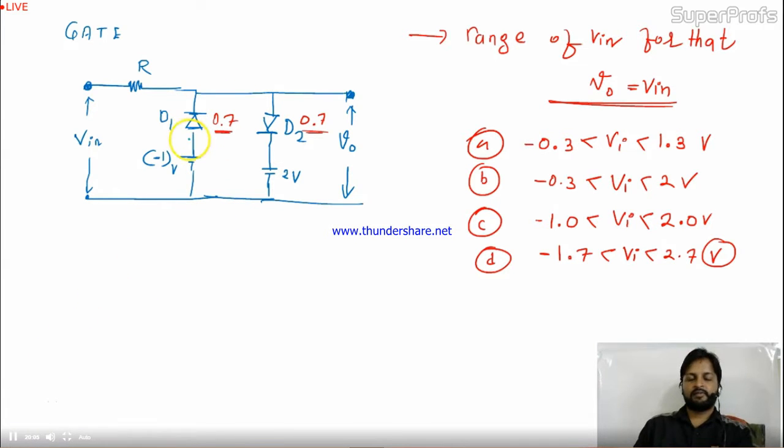Let's start it. So now I will remove these 2 diodes and will apply this 0.7 volt. Okay. So the direction of the diode is given like this. So the positive terminal of the battery should be this side, and for this, these are opposite to each other. Okay. So let me clear this first, so it will be easy to understand for you. Okay. This is 0.7 voltage drop, and here the drop is to this side, 0.7 volt.